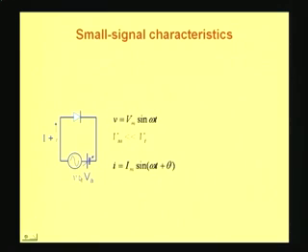The magnitude of this voltage is small, so that is why the term Vm is said to be very, very small compared to the thermal voltage Vt. Now why should Vm be much less than Vt? Well, at this point this is not clear. It will become clear when we take up the details. The frequency of the signal is omega, as shown by the equation. The small v is equal to capital V suffix m into sine of omega t.